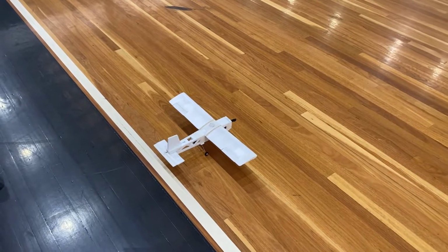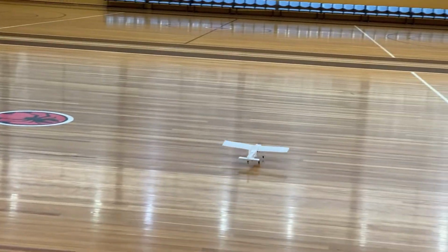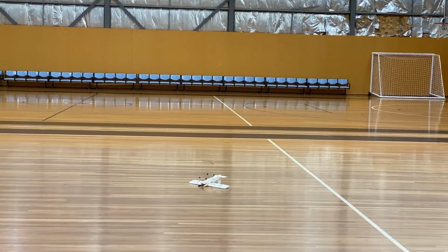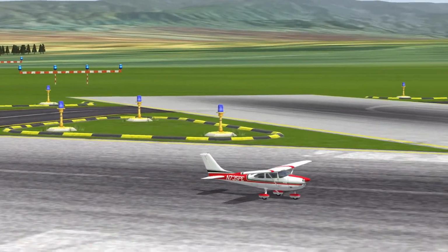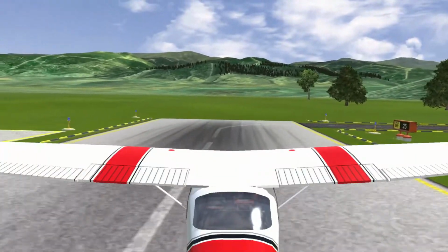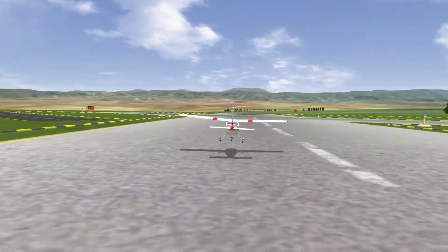As the chosen pilot for this project, I struggled a bit with the unfamiliar platform. It became evident throughout the testing that the skill of the pilot was a significant factor in the success of the plane. Lacking the experience and not wanting to completely destroy the plane, I wasn't fully committing to flying fast enough, which was partly the cause of our control and lift issues. The other control issues came from not increasing the aileron size when we increased the area of the wing, a slight oversight. Practice and confidence were gained through use of simulation software provided by the teacher. Practicing on the computer, I was able to learn how to control the plane in a risk-free environment.